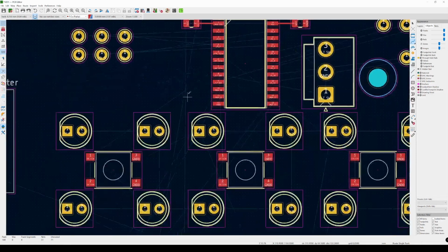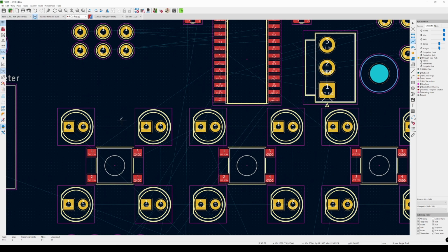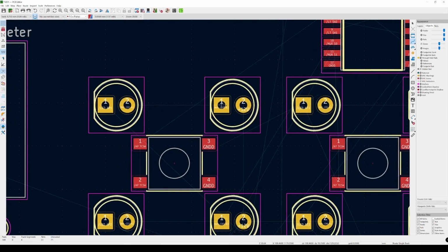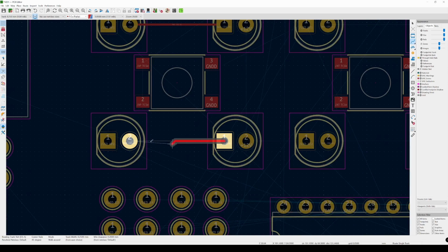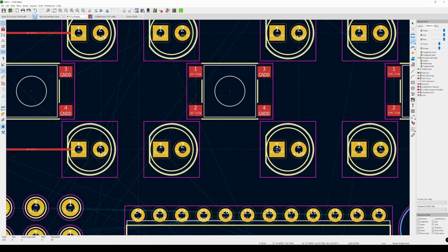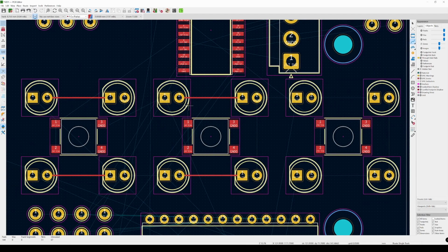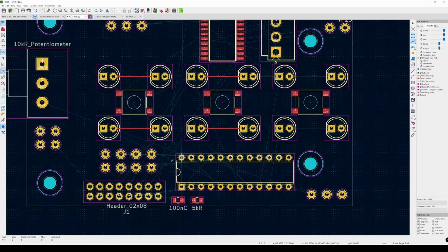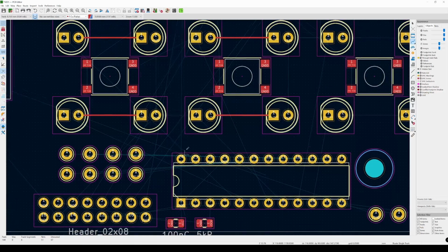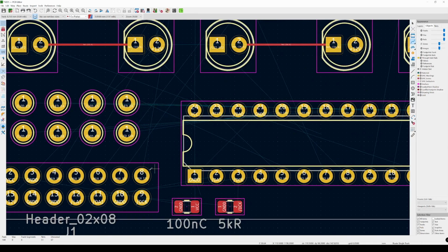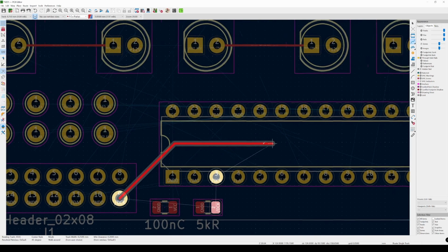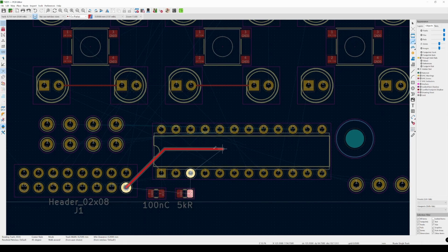Now the blue wires indicate unconnected pads, and they show you where the connection should be made. For example, here we have a very simple line going right there, again right there, right there, and this is basically what you need to do for every single component. Things can get very difficult, but one thing you need to realize is you can always go underneath the components, so you're not confined to the outer limits here, but you can go in here, you can go through there.